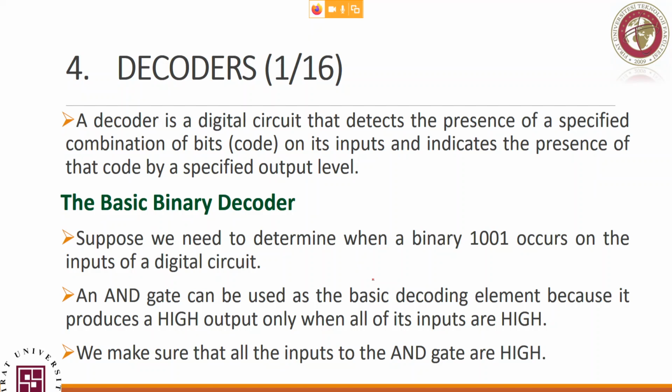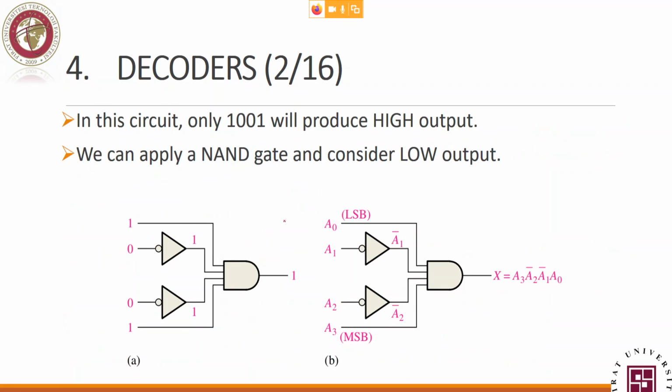All right. Decoders. Decoders actually are circuits that give you a high output based on a certain input, or specific input, or decoding a specific input. Decoding means what? Running a process of, you can say, Boolean algebra or some kind of digital operation on an input that provides a high only in one case. And in that specific input, we are decoding a scenario. This is the idea.